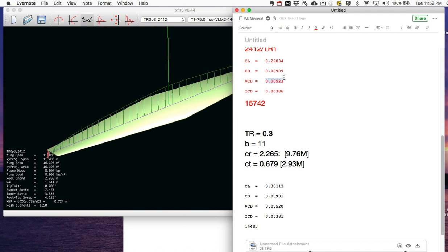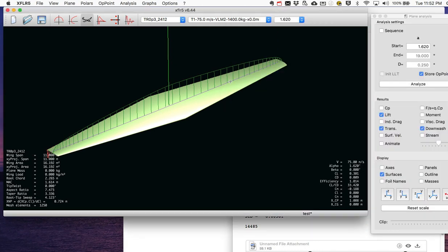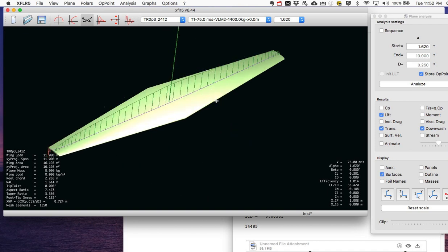They are somewhat coupled. When you change the planform, you change the Reynolds number, and that will have some effect on the viscous drag. But it's sort of preliminary analysis in terms of eliminating, I would say, classes of foils and figuring out what might work for foils. You get a sense of what kind of Reynolds numbers you're dealing with. Here we're dealing with kind of like 5 million. That's sort of our Reynolds number.